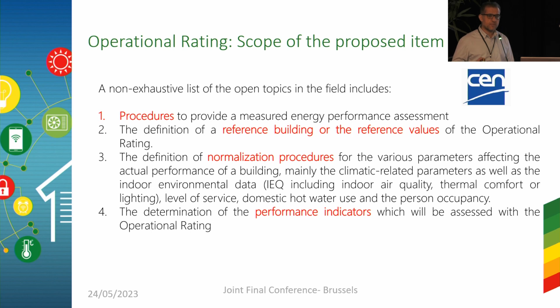So the vast majority of the member states just provide an energy performance indicator in terms of energy per area. These, though, may not be sufficient and may not deliver comparable results as with the case of the asset rating, meaning that we do need to have some joint understanding and some joint definitions concerning the reference building for the operational rating. Also, as we have seen earlier, the 52,000 standard series recognizes the fact that we cannot just use measurements to deliver an operational rating. We need to correct these measurements.